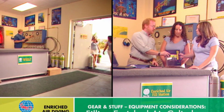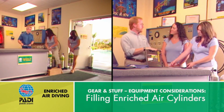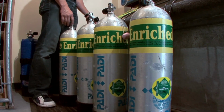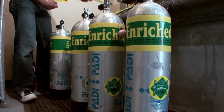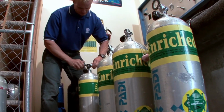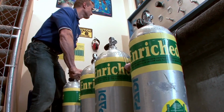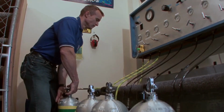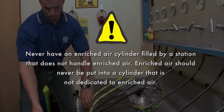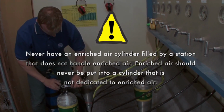Filling enriched air cylinders poses two concerns that you don't have filling a normal air cylinder. The first is a fire or explosion hazard. Trace lubricants and other contaminants can accumulate in standard air cylinders and pose an immediate hazard were someone to put pure oxygen in the cylinder. This is why blenders use oxygen-compatible air for partial pressure blending. Never have an enriched air cylinder filled by a station that does not handle enriched air. Enriched air should never be put into a cylinder that is not dedicated to enriched air.